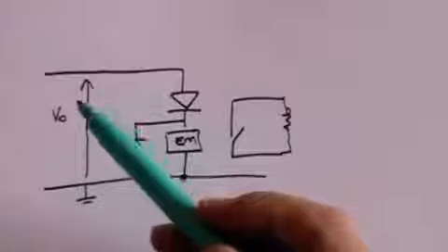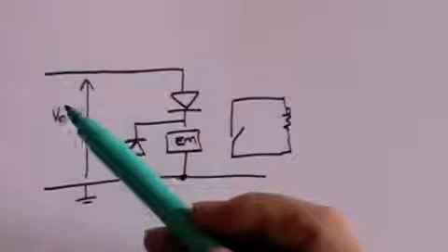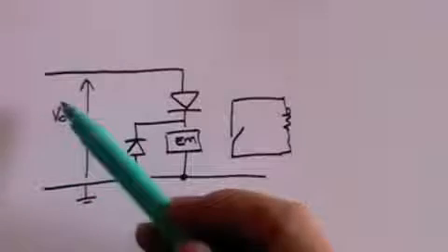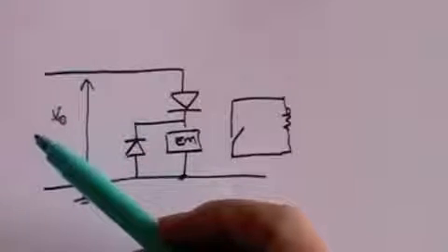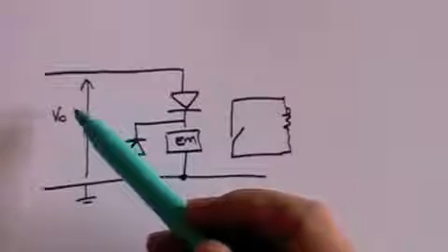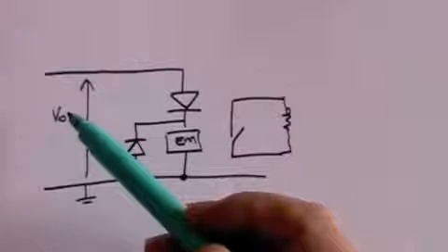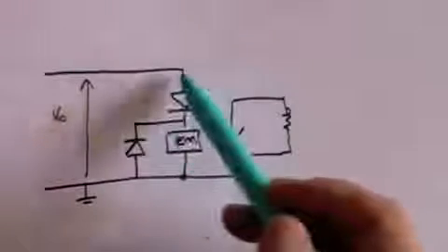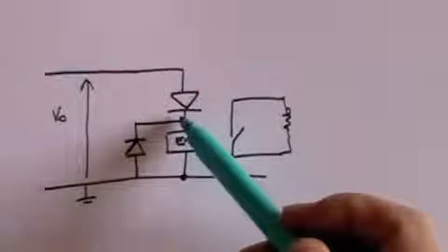So for example, let's say you needed to switch on a light in a room when it gets dark. You would arrange for your sensing device and your operational amplifier to generate a negative voltage so long as the light is strong. And that means whilst the light is strong, no current flows down through this diode.